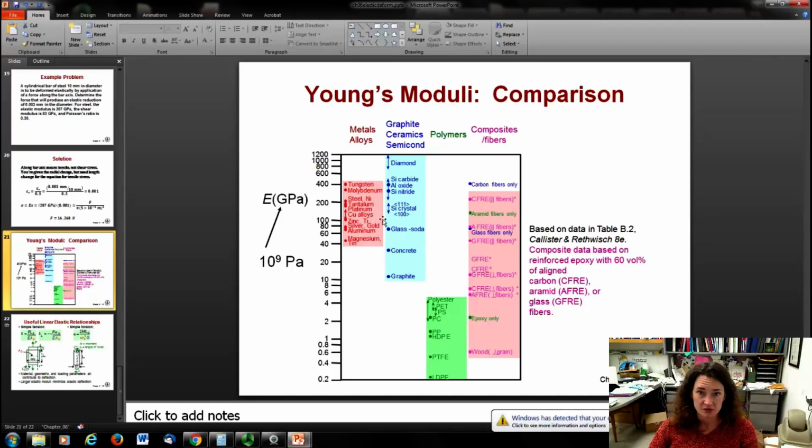What might be a little surprising to you is that the stiffness or modulus for the ceramics is actually comparable and in some cases even larger than the stiffness of metals. Okay, and as we'll see and discuss, yes, these things are very stiff, they're very resistant to changes, and they also break like crazy. So you can get a metal to stretch out, you can draw a metal into a wire, not so much, say, quartz, okay?